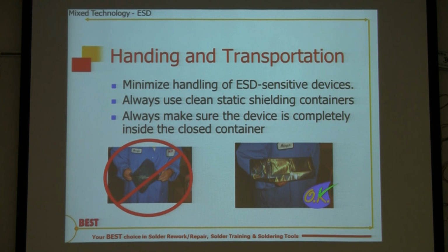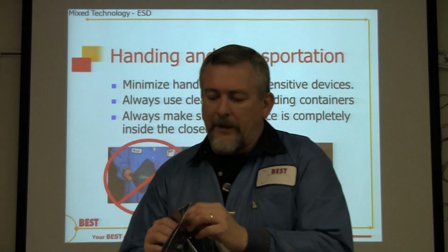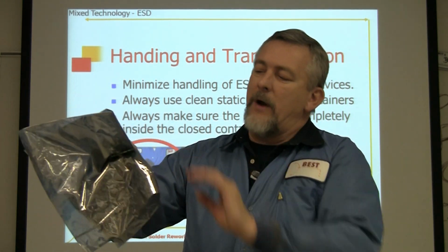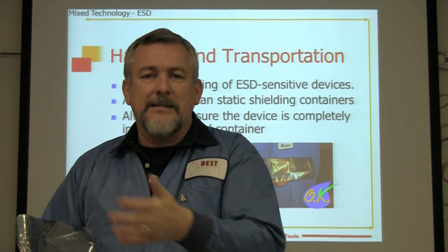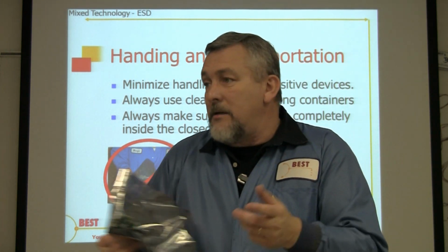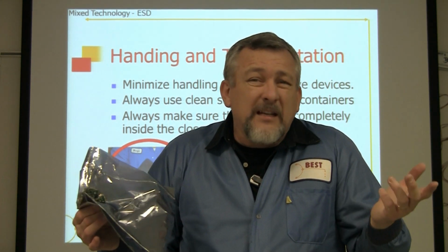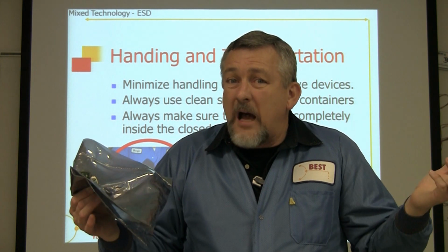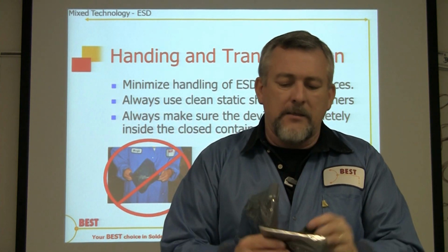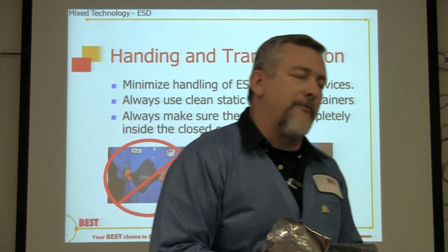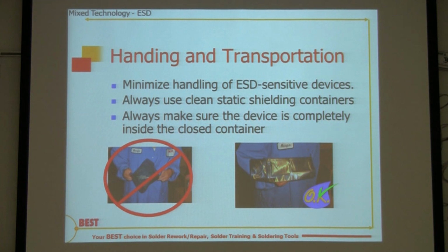Let's grab that board real quick. We want to take it down to Billy. I got a component that needs replaced. So what do you do? You do this. I call it the Taco Bell carry, because you wrap it around it like this. This is not being protected whatsoever, and you go down there. So anything that's ESD sensitive on there could be walking past something that's plastic, it's rubber, it's a non-conductor, and it's going to discharge into the component. So don't do it like this. Again, put it inside the bag to transport it from point A to point B. Okay?